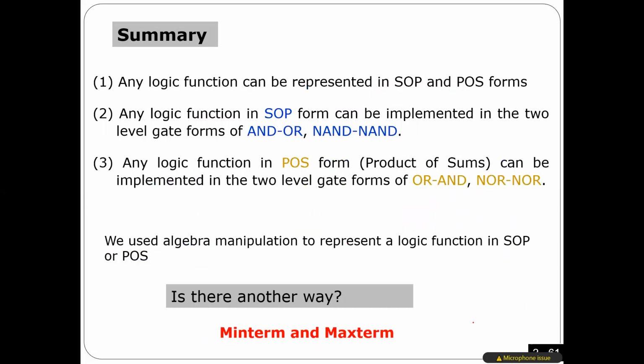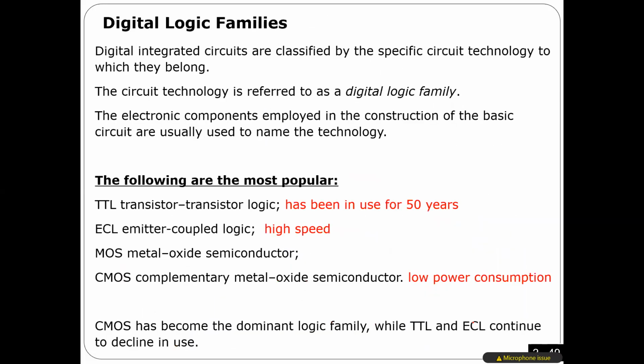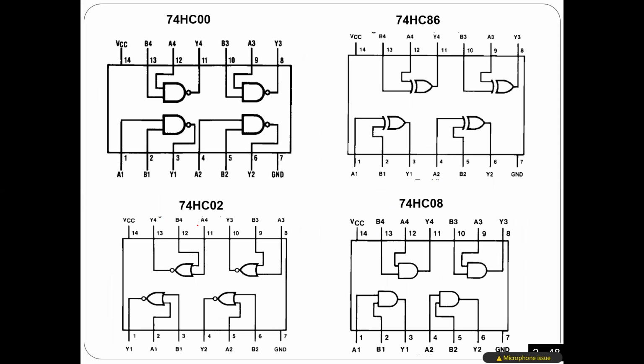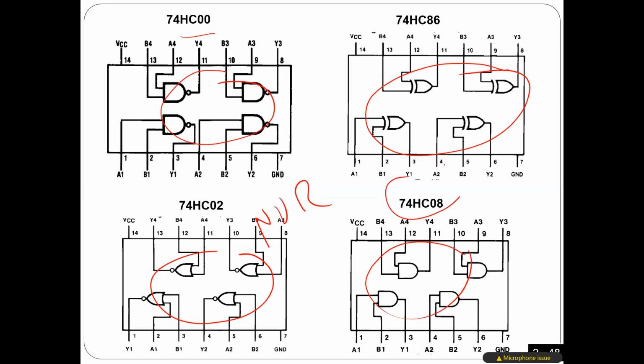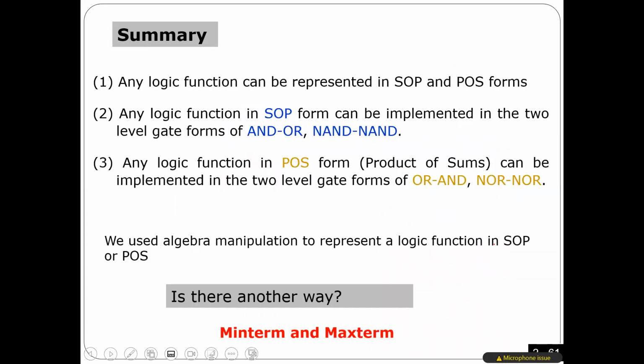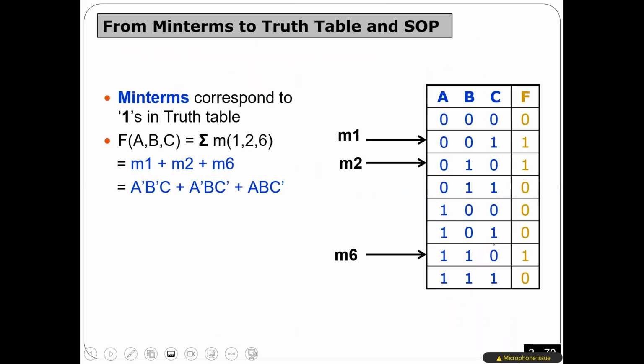By the way, you have other chips, so that's why you need to look. Here we have another chip from the 74 family as well. This one has 4 NOR, 4 OR. This one has 4 NAND. This one has 4 exclusive OR, which is what I explained last time. This one has NOR. These are the same family but different numbers, okay? So these are NAND. Anyway, let me come to the point here.